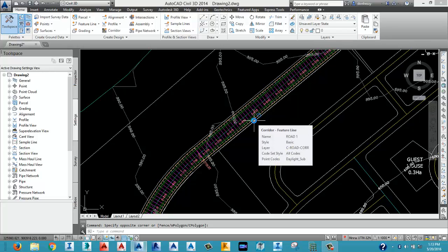That's what we call plan and profile production. Then after plan and profile production, you can proceed to generating your typical cross sections at various intervals. Those are the guiding documents requested by the authority or agency whenever you are doing a typical road design. If you are making a submission of your design, they expect you to produce your plan and profile based